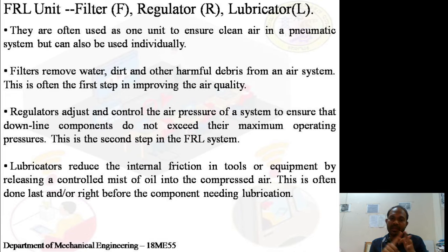Whenever there is a loss of material, you will hear a sound. You will hear the failure of the material. There will be a complete failure of the system itself. So lubrication is very important. One more point is, with more friction, wear is also more and the heat generated will also be more. Thermal stresses will be generated. So friction is a hero and friction is a villain also.